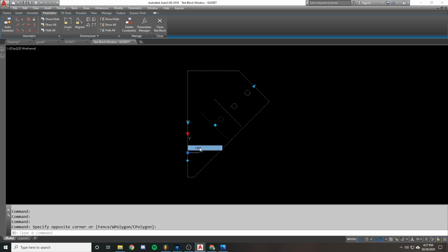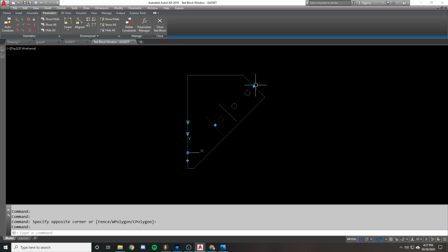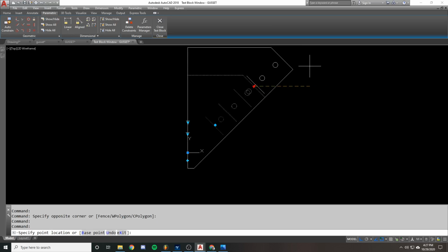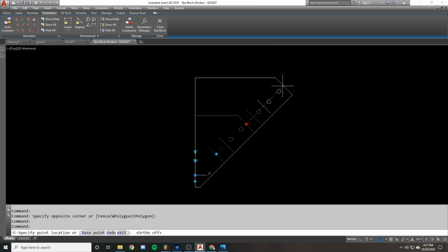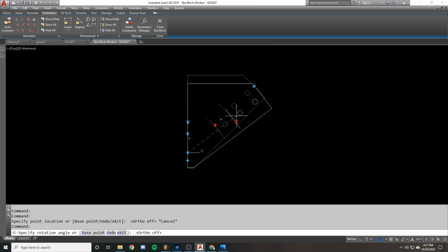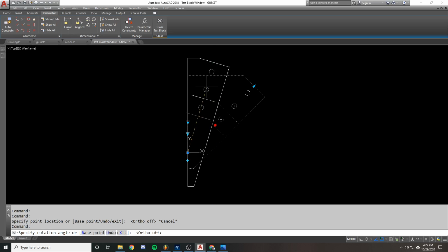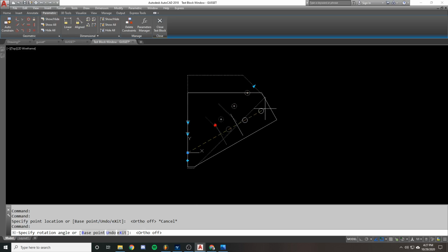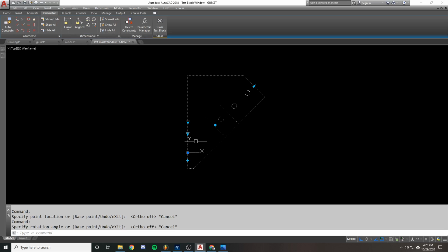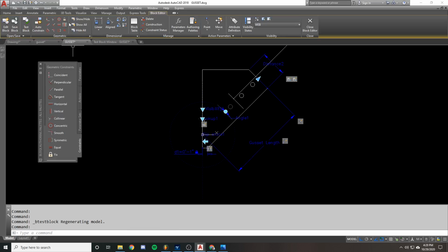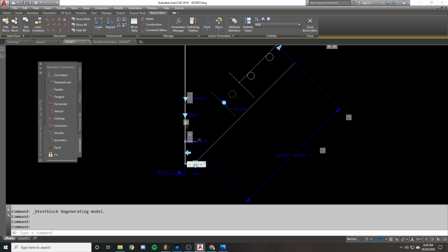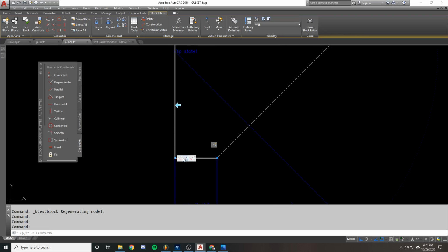Again, changing the sizes and all that, and then of course, giving that extra length if I need to, and then being able to rotate it. The only thing I haven't done to this one is put in a limit to the rotate parameter, which wouldn't be a bad idea, so somebody doesn't go too far and try to break it. But it works. I mean, it works pretty good, and it's got all of those constraints in there. Hit show all. You can see most of the same constraints are still there. And I did want it putting perpendicular in here after all.